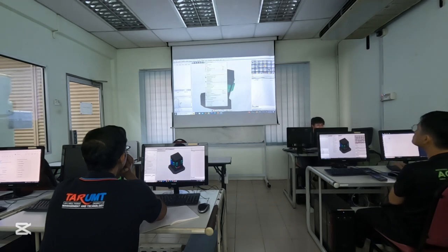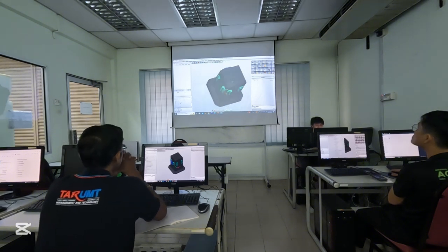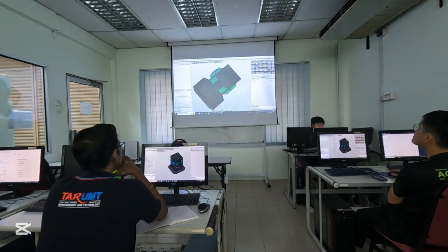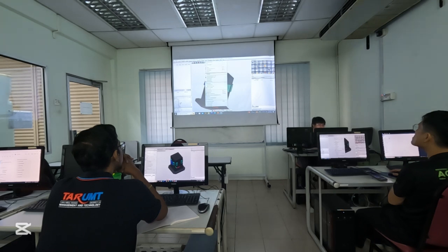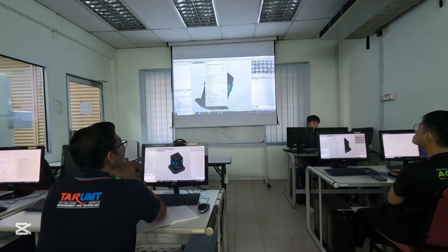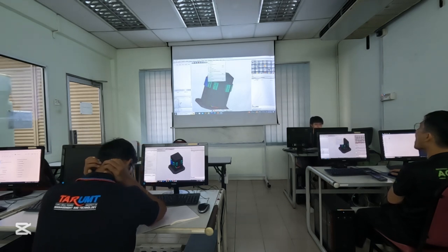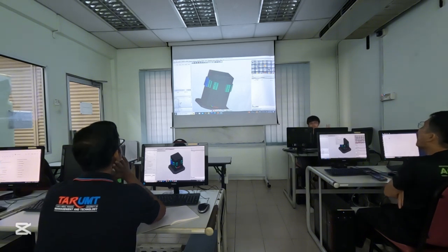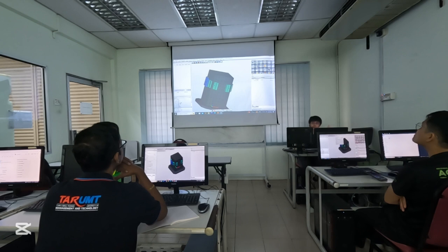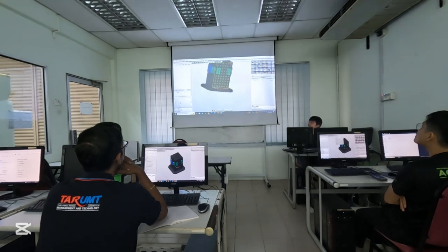And then view is just your view. You can change how you want to look at things, and maybe you want transparency on or off. You can change to see left, right, up, down, the normal 6 ways. Then workplane is where the datum of your program will be, depending on how you set it. You can set it anywhere. So for this, it's on the bottom. This is the work plane, but you can furthermore create more work planes other than this one.